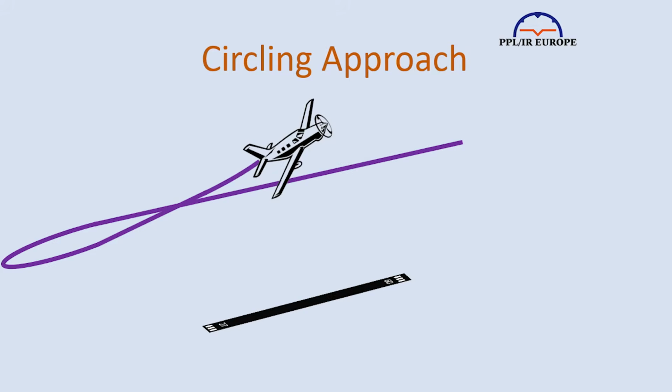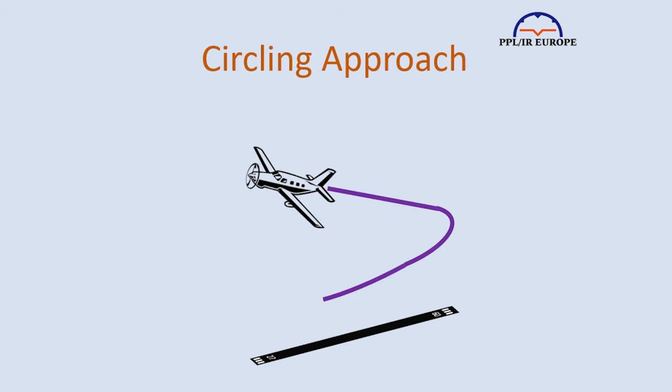Unless the approach plate says otherwise, the missed approach procedure is based on the initial approach runway, not the landing runway. The first action is to make a climbing turn towards the landing runway and overhead the airfield, and then to manoeuvre onto the missed approach track. This can be achieved either circling or in an S-bend. This can be a challenge as you may be pointing in exactly the wrong direction.